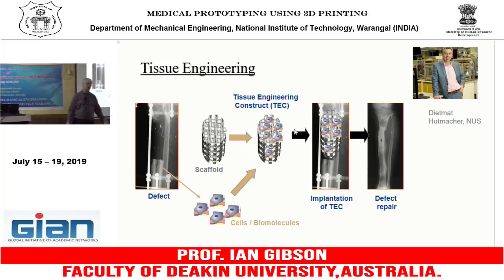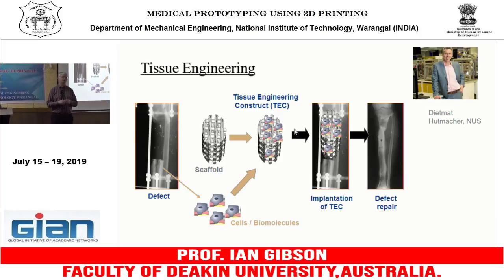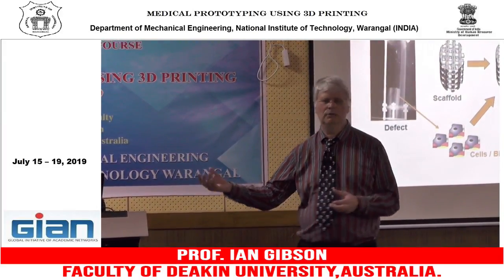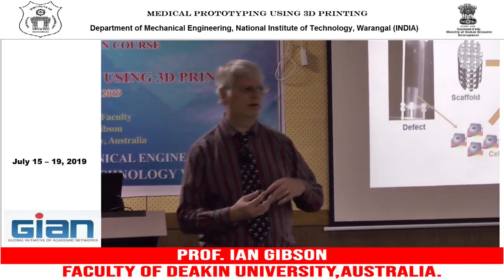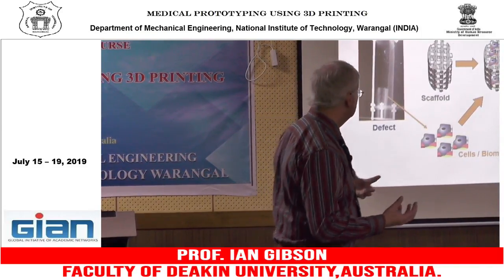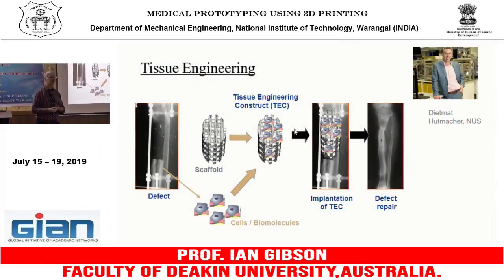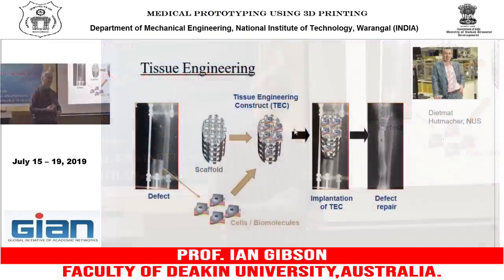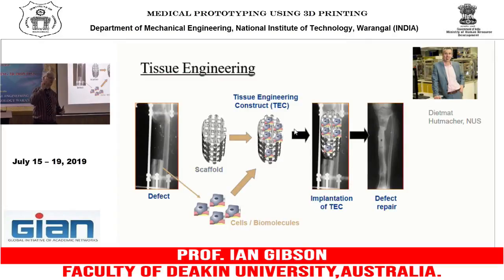Basically, we were working with a blended material. The polymer was polycaprolactone, PCL, and we were filling it with a ceramic powder, tricalcium phosphate, TCP. So we were building PCL-TCP scaffolds. The trouble is that when you blend these materials together, it's extremely viscous in the melt. And conventional 3D printers would extrude, but only in ratios of up to about 15% by weight of the TCP. And we wanted higher. We wanted at least 30%.